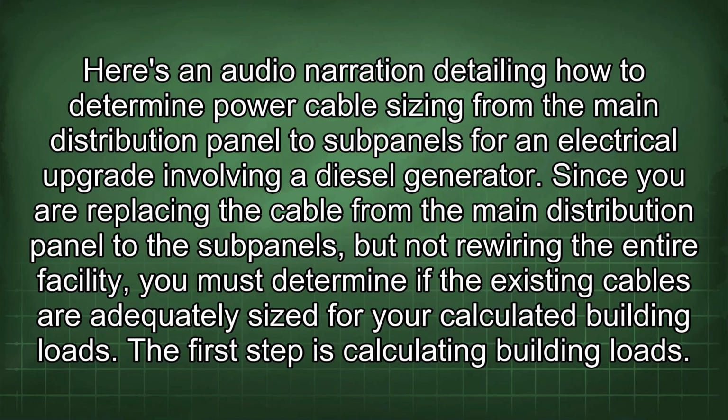Here's an audio narration detailing how to determine power cable sizing from the main distribution panel to subpanels for an electrical upgrade involving a diesel generator. Since you are replacing the cable from the main distribution panel to the subpanels, but not rewiring the entire facility, you must determine if the existing cables are adequately sized for your calculated building loads.